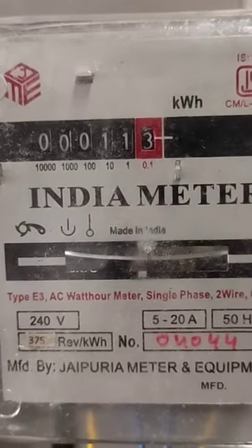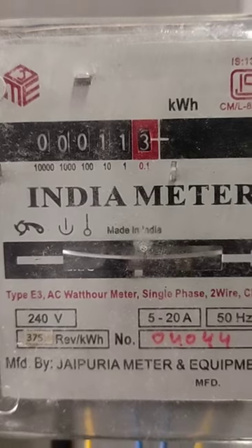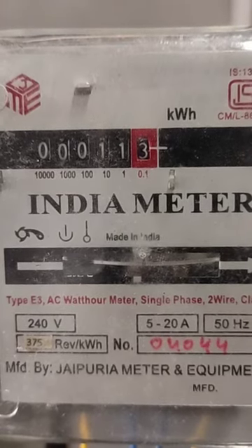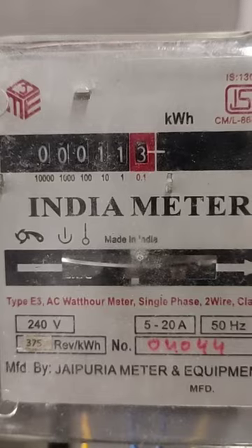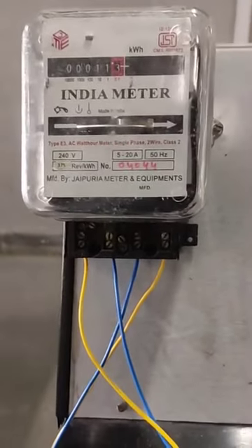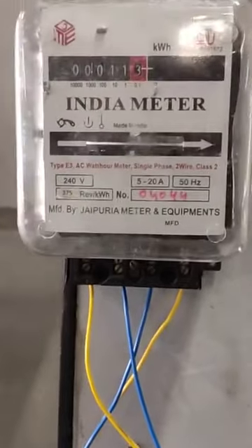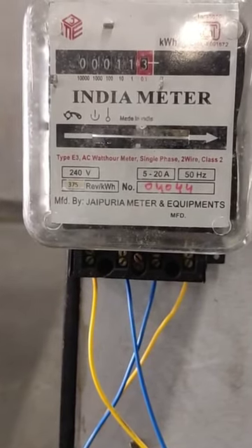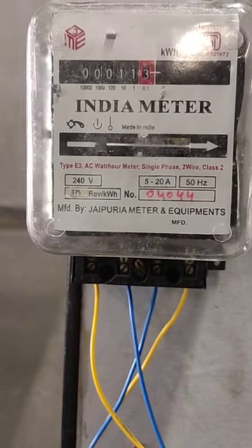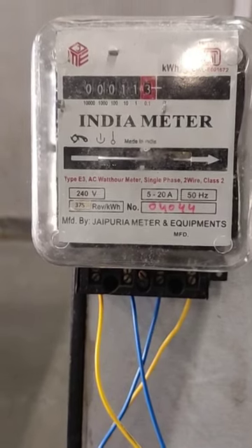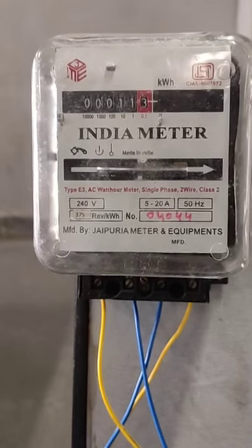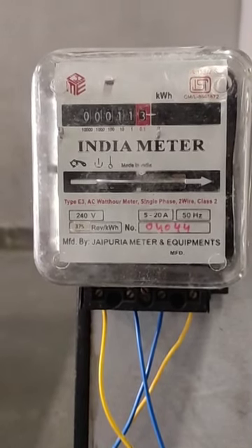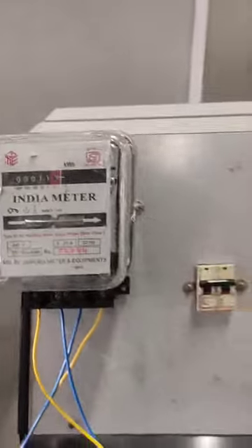You can see the rotation of the energy meter. The black shading will be there. You can see the black shading now it is passing. Let me show that once again. For another revolution, you can see the black shading in the energy meter disc. Just observe keenly: one black mark on the disc represents one completed revolution. You can see now it is crossing. So 2 revolutions got over. Accordingly, note how many seconds it took for completing 3 revolutions.